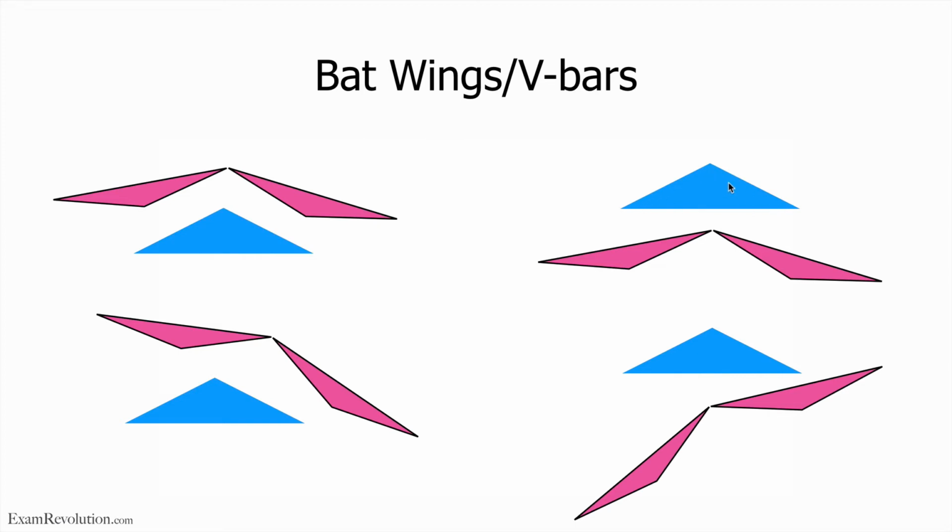Over here, there's your aircraft and the bars are showing down, right? So you just need to pitch down and put the triangle into the bars over here. In this case, the bars are up, so it's away from you and it's banking right. So you have to pitch up and bank to the right. So just see yourself putting this triangle in that position over there. And you can see it's banking to the right and it's a little bit up.